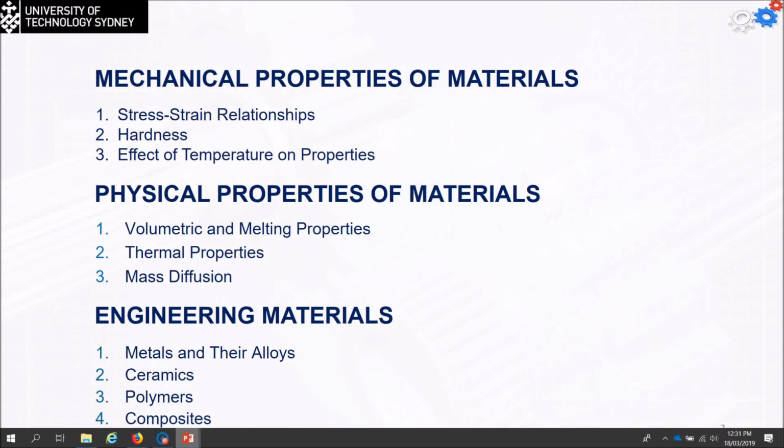Usually, most of the materials have some elastic range, and if they pass a certain stress value, they go to the plastic range. So elastic means that the minute we remove the load, the shape will return back to the original shape. If I pass the plastic region, every force I add is going to cause a permanent deformation to the material. And that's actually the main important thing we have in manufacturing.